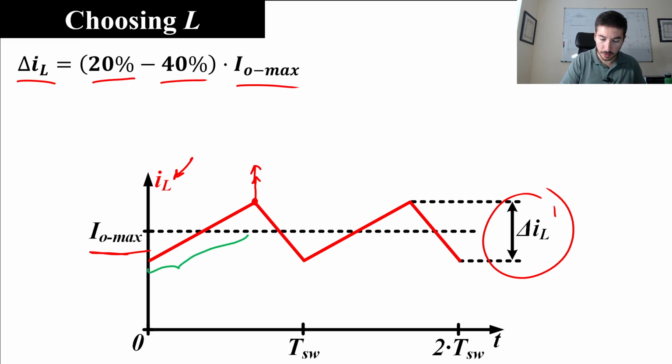During state 1, this current is driven by switch A, and during state 2, this current is driven by switch B. So if we increase the current ripple, we increase the maximum current that the switches must drive. Basically, that translates into higher cost of those switches and in general a higher size of those devices. So this is something that we don't want, and that's why we put that rule.